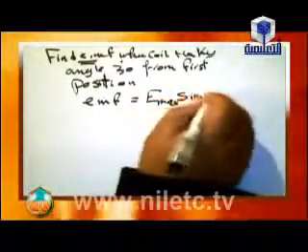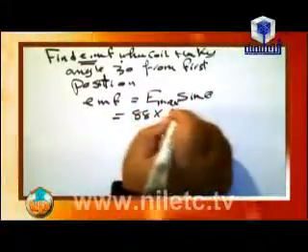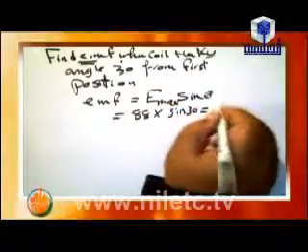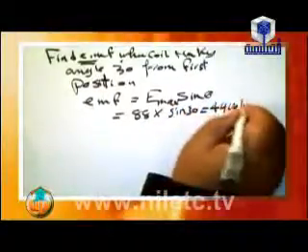EMF equals E maximum sine theta, then equals 88 times sine 30, which is equal to 44 volt.